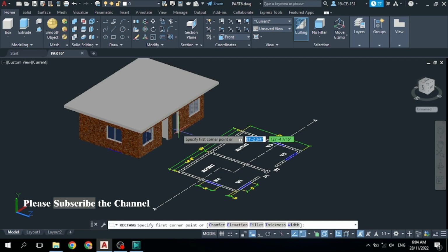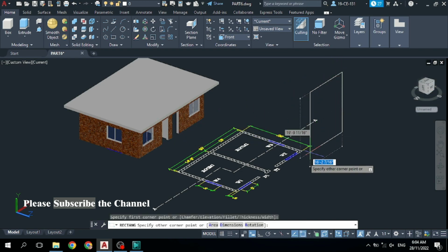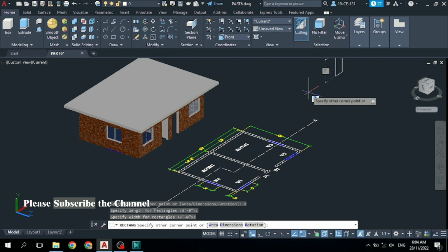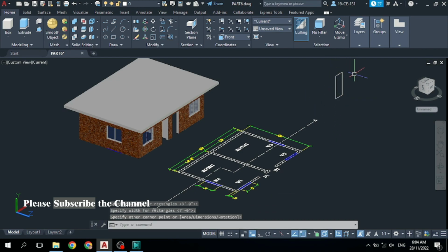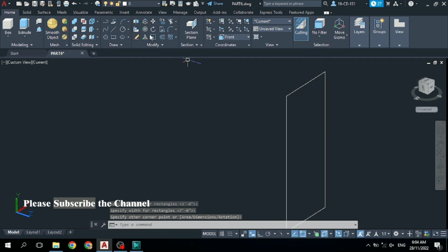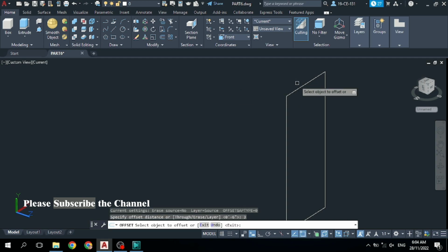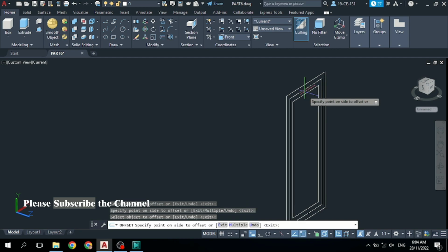You know that this door is 7 feet in height and 3 feet in width. For that start the rectangle from this point and click on this dimension, and you know that the width of this door is 3 feet and height is 7 feet. Now you can see this rectangle, it is a door frame. And after that click on this offset command. Type, let's say, 3 inches offset distance, and click on this rectangle and come down.